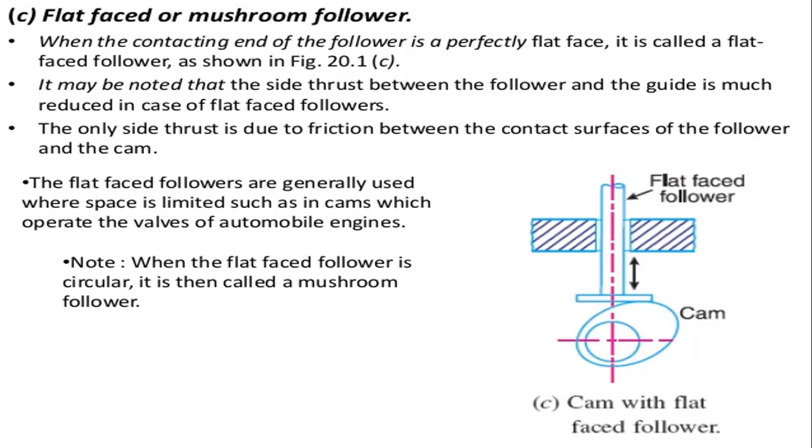Next, it may be noted that the side thrust between the follower and guide is much reduced in the case of flat faced followers, because these move in a straight way with no deflection, and the contact surface can be any point on the flat faced follower. It has a very wide flat face, so we can touch it at any point.